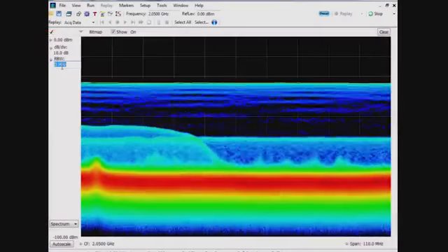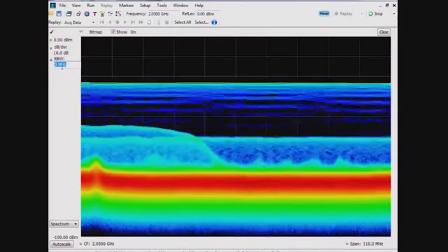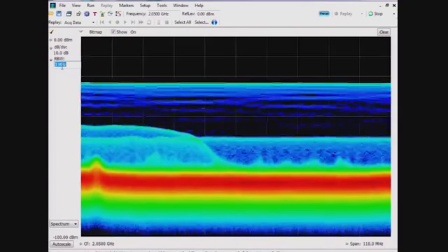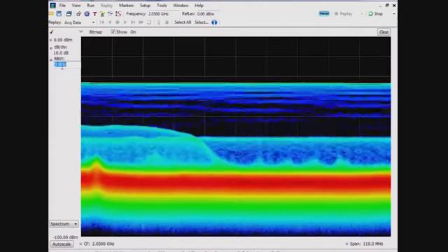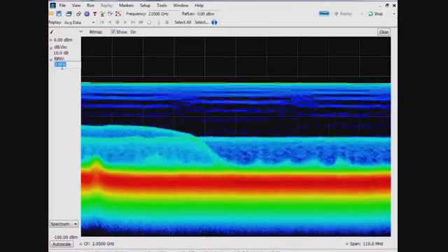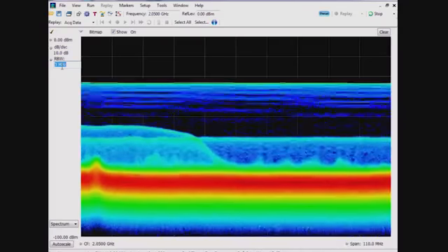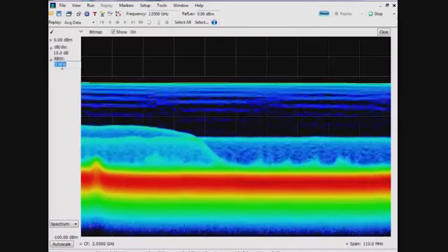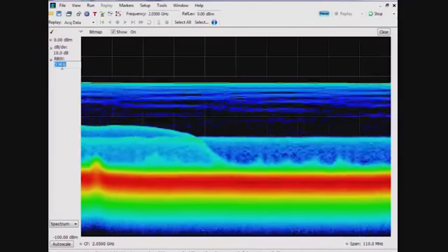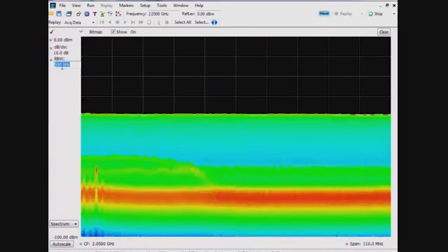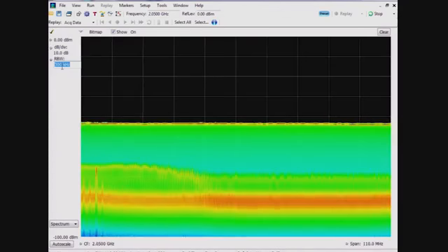The first key point to show is how Tektronix has established the most advanced real-time signal analyzer. In this example, we see the DPX display, which in this case means digital phosphor spectrum. Here, the RSA displays nearly 300,000 FFTs a second. The RBW, or resolution bandwidth, is quite flexible here, and I can control this like a traditional spectrum analyzer. Here we are looking at the instrument's entire 110 MHz real-time bandwidth.